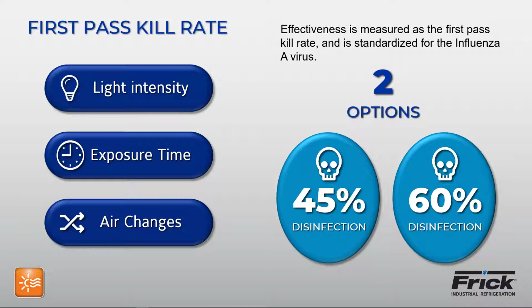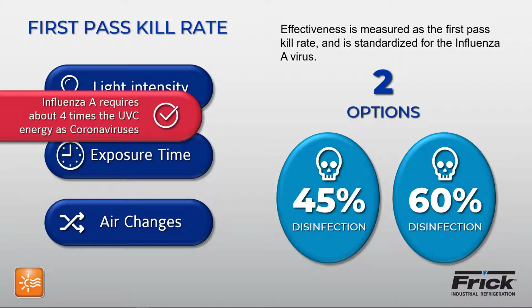Recognize that in our applications there are relatively high air changes, so the overall number of pathogens will continue to fall rapidly with either of these options. Also note that coronavirus is easier to render inert than influenza A.